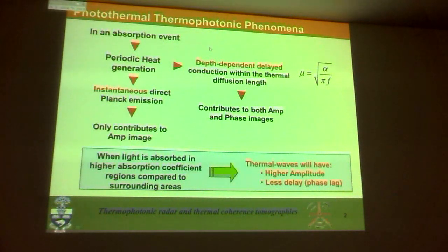It's just a question of how do I do it, and how do I do it to beat the diffusion? So part of what I'm going to present is, first of all, how does photothermal detection work, which is modulated detection, kind of pulse photothermal, but I have been using modulated for the same reasons I'm using for acoustics, because you can actually get those very high signals against background.